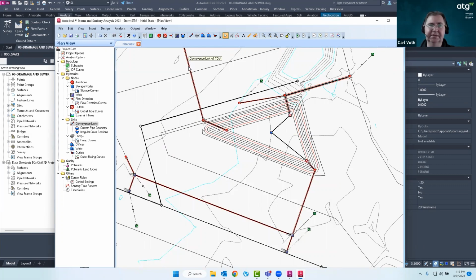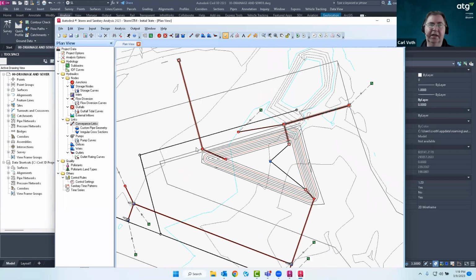Now this system here, if you remember, is our outfall system, and we're tying into an existing ditch, and we're not really using an outlet control structure because, as we found out, that pond was oversized for this drainage area. So we're just using our pipe here as our restrictive control structure instead of actually putting in weirs. But I'm going to show you how we can go through and do that.